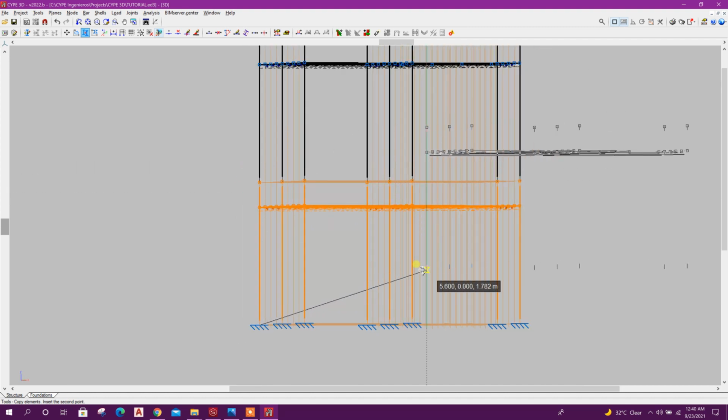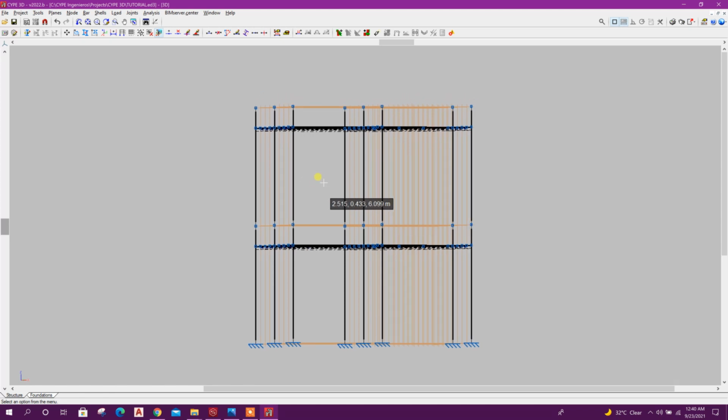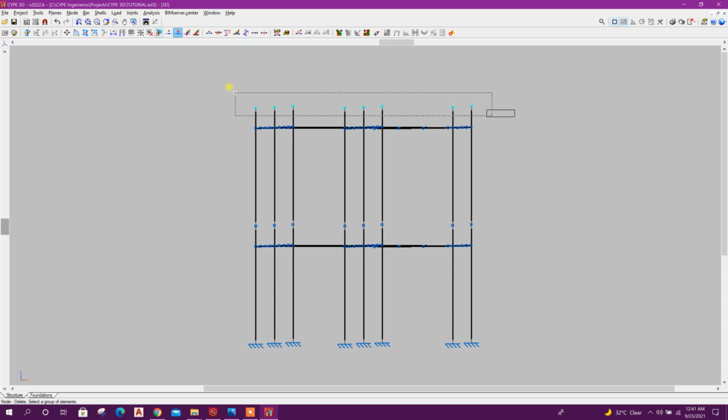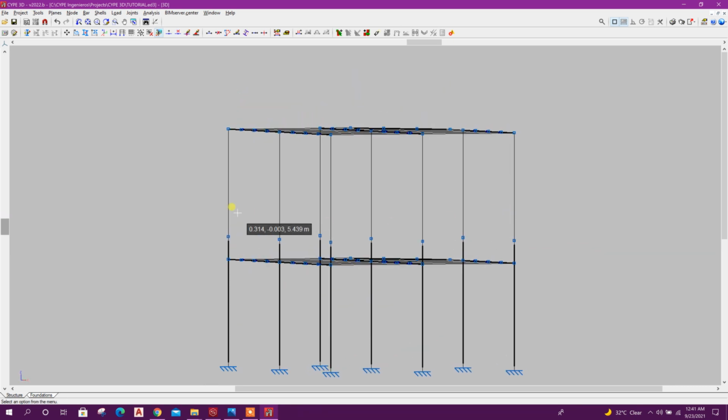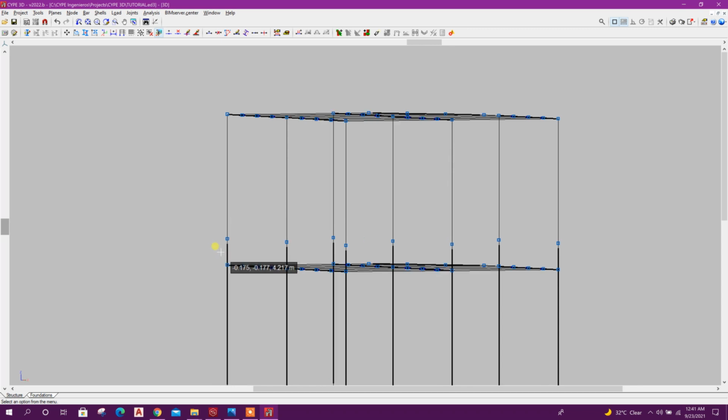here. As it is two-storied steel structure, so we will delete the extra portion of columns. Delete. Using this one we can delete, or if we want to delete member with node, then we can choose this option, delete nodes. Select the nodes, right click, like this. Now here our floor height coming 0.8 meter plus 3.8 here.